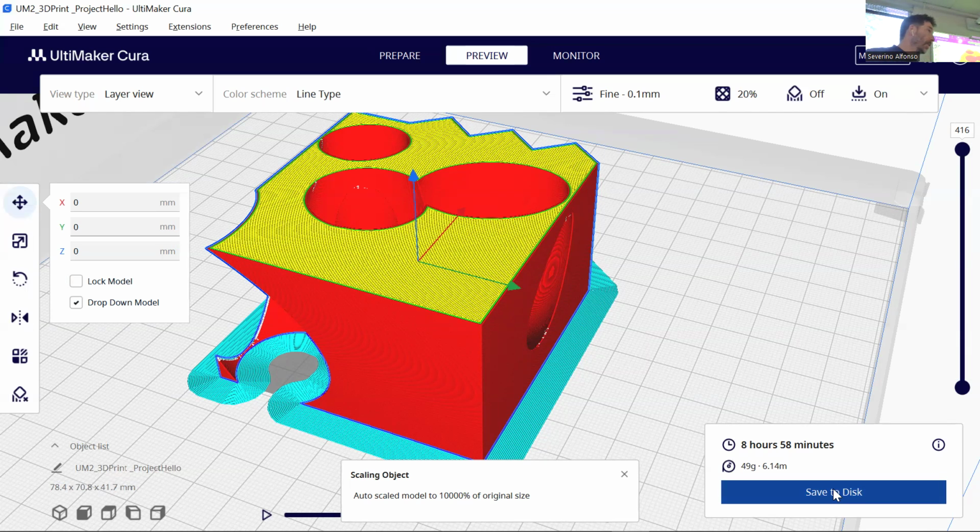One out of 3 times, or maybe 4 times, it's going to fail. So I recommend that everybody stays nearby the machine and takes a look at the first 2 layers. If the first 1-2 layers are good, chances are it's not going to fail. Okay, so you can go, you're not going to stay 8 hours, 3 hours, whatever, you can go and just return at the time that you expected.